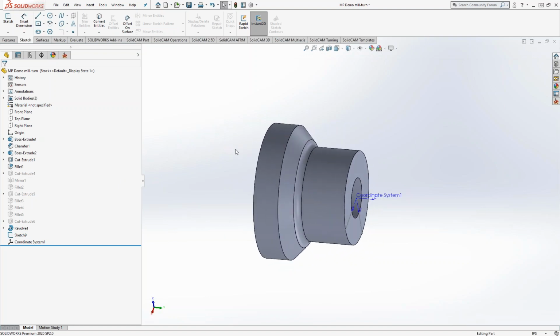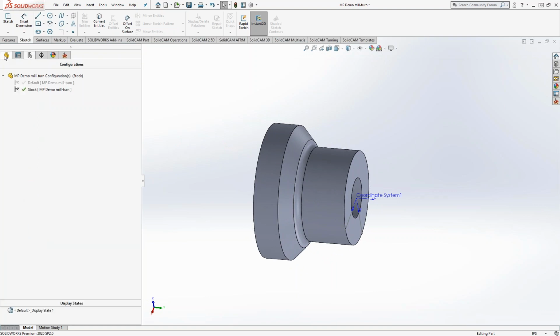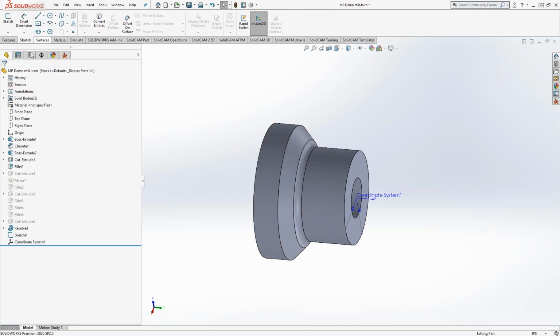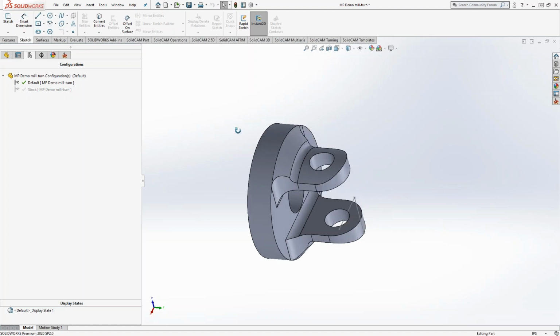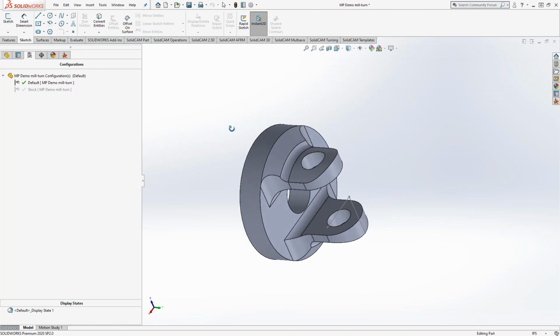And again, it's a single solid that I'm dealing with. The use of configurations allows me to do that. I go to the feature tree, suppress something, and then when I go back to the configuration manager, I can just return to the default, which has all those features still turned on. Okay? So configuration allows you to make two different versions of the same part. Certain features suppressed, certain features turned on in certain cases, but I actually have one part file that I'm dealing with that has two versions of it.